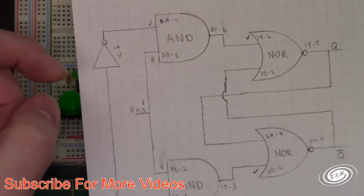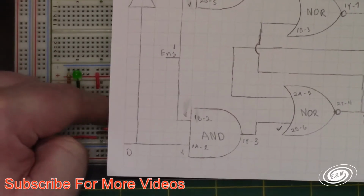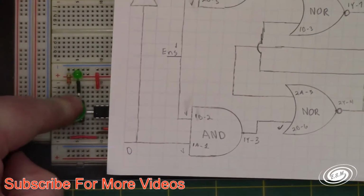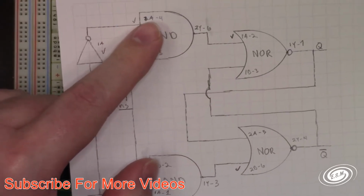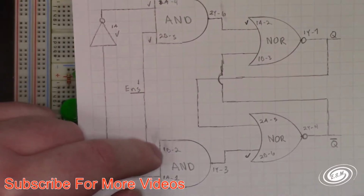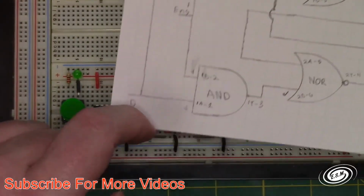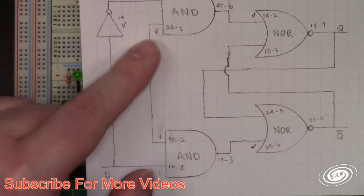And then I have the other side of the inverter, which is 1Y, which is pin 2, and that is going to pin 4 of the AND gate. I tied pin 5 and 2 of the AND gate together, and then I brought the enable over and plugged it into pin 5, the enable signal, so that enables it.